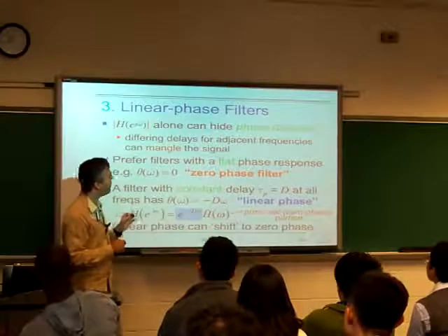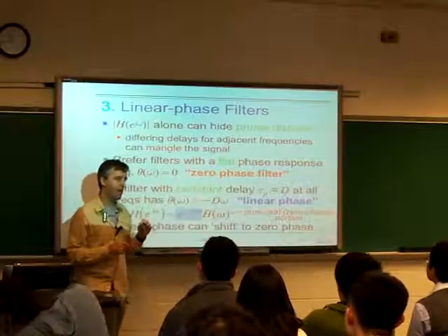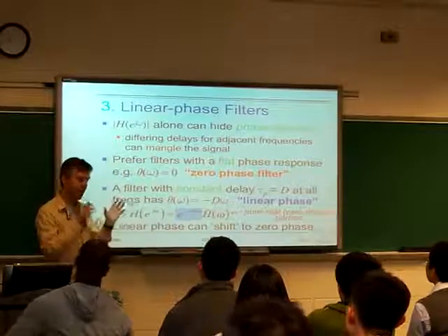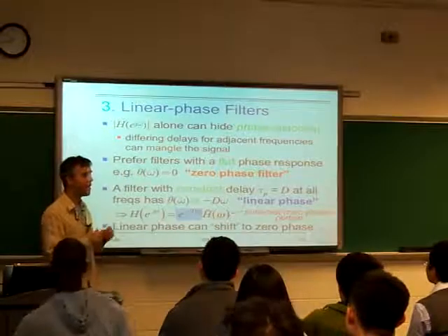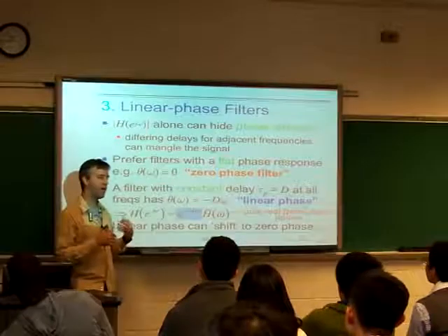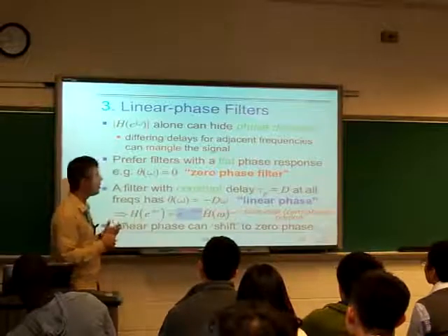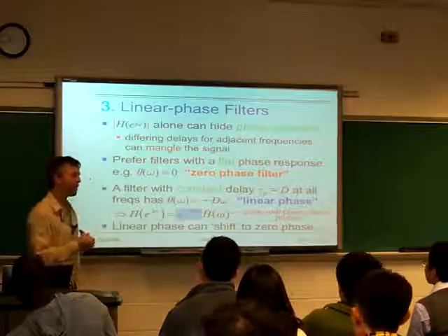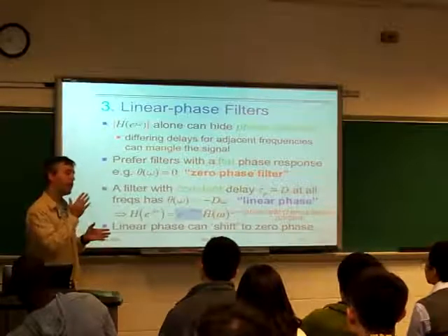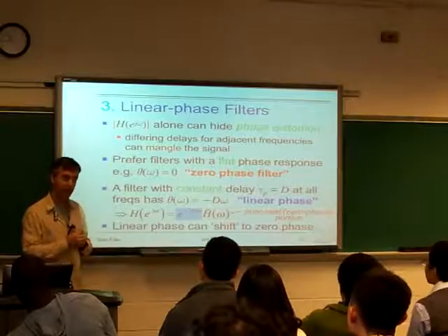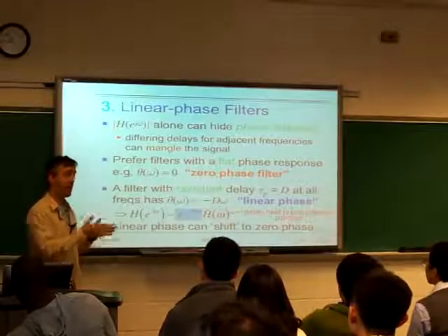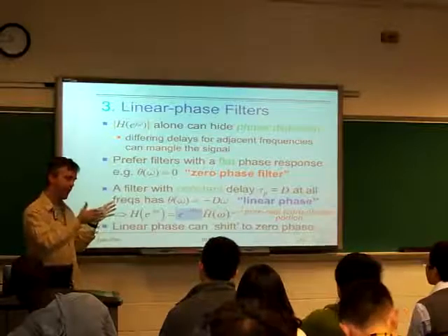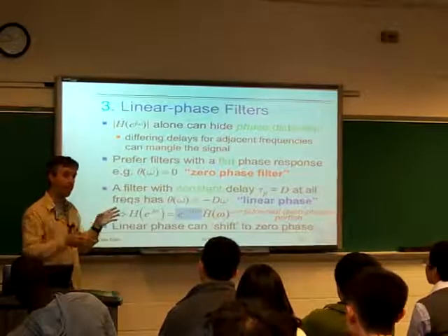But in the phase domain, it turns out that the ideal phase characteristic, which is no phase shift for any frequency, is something which is either attainable or close to attainable, in the sense that we can build a filter which maintains the alignment between the phase of all the frequencies. Maybe a sinusoid experiences a particular delay, but the delay is the same independent of frequency.